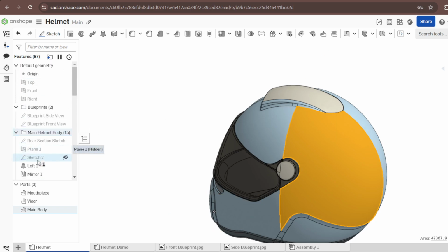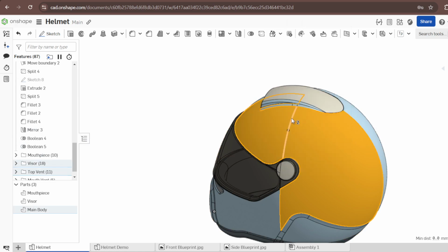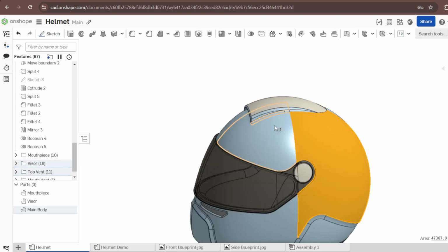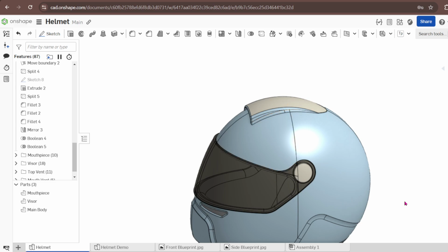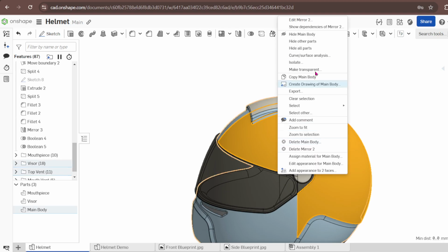If you go back here, then you can see this profile there. These two surfaces, they meet at this edge. You can see this is where they meet, and this surface has to have tangency continuity. They have to be tangent, and we can check this tangency. Let me see if I can do analysis here on the fly.